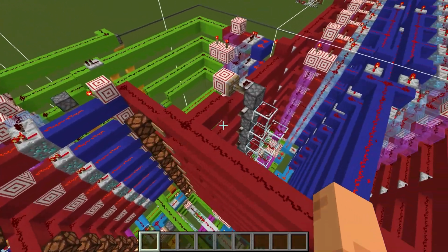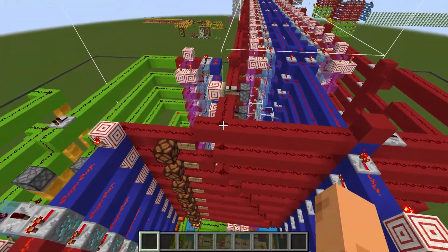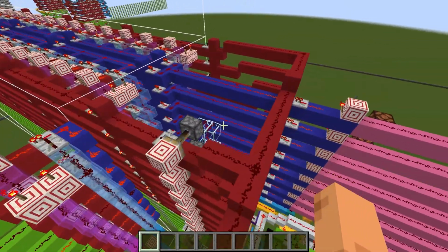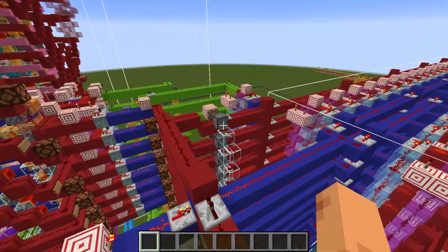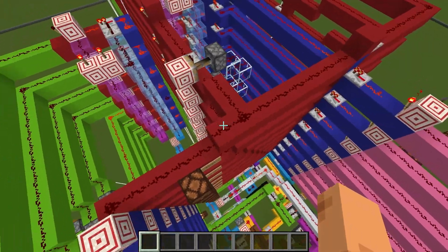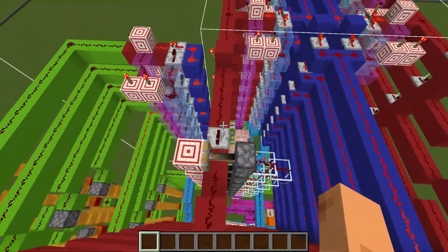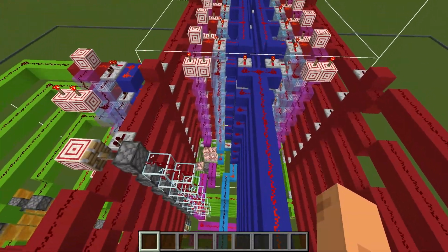So it's somewhat of a typical optimization where you do two things at once in parallel. You read the odd side and the even side at the same time, and then you have an opportunity to use both of those values without doing a whole other read cycle.